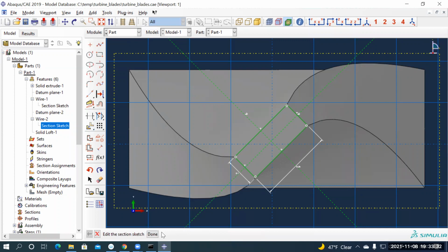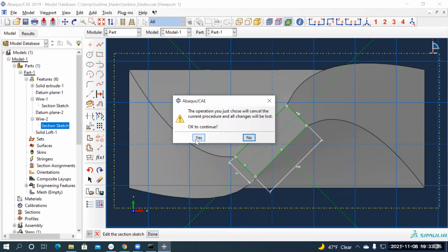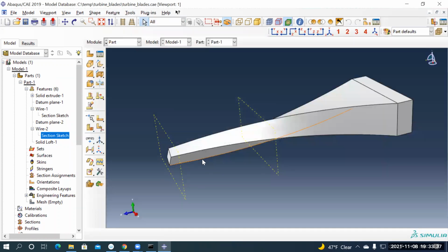Did that work for you? Maybe. Now try lofting once you have all the three sections centered. Try lofting. Solid, loft. Insert before. Okay, draw a box around it. Insert before. No, careful. Go back. So select section 2. Insert before. Yeah.